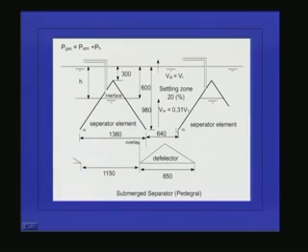So, what is happening here? We will be having a high velocity and it will be gradually decreasing. So, a velocity gradient is available. So, flocculation can occur, and this will be acting as a sedimentation zone also. So, all the biomass will be getting settled here, and this is having an angle of inclination of 45. Because of the self weight of the sludge, whatever is settled here, everything will be coming back to the reactor.